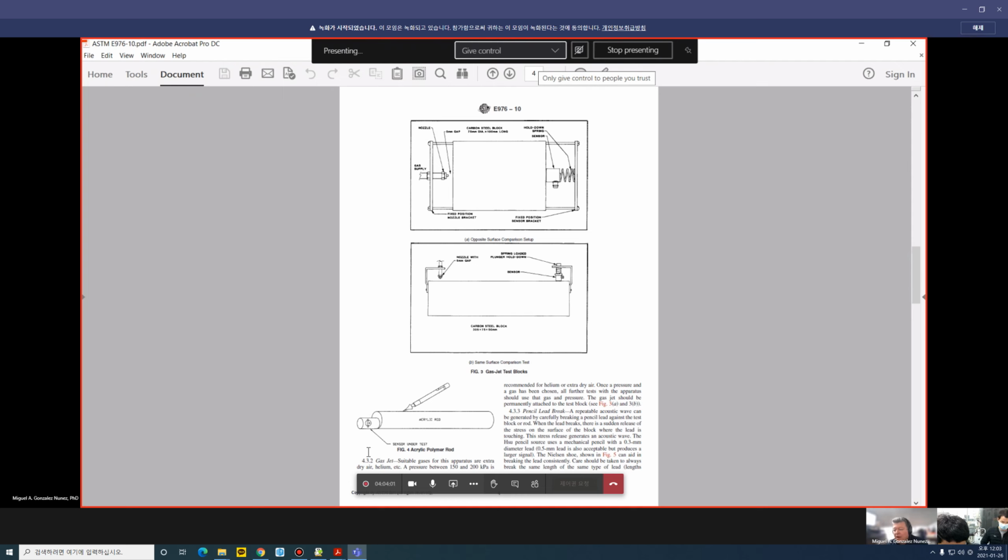And that's how you can have a reference, to see if the sensitivity of the sensor is good or bad, or worse, depending on the couplant that you are using. So what if the sensitivity is lower than the reference? Well, you can make an estimation. You can have a relationship between the good coupling and the coupling that you have in your real application.